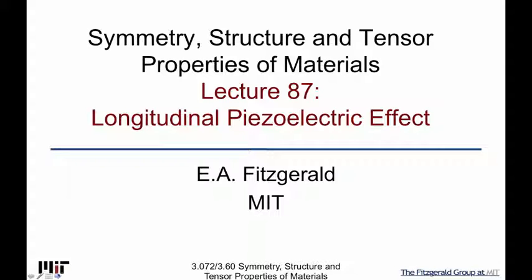So we'll begin by first talking about the longitudinal piezoelectric effect, which is a way to do that, and then we'll talk about the symmetry effects and how you can really simplify a lot of the D_ijk tensors through crystal symmetry.